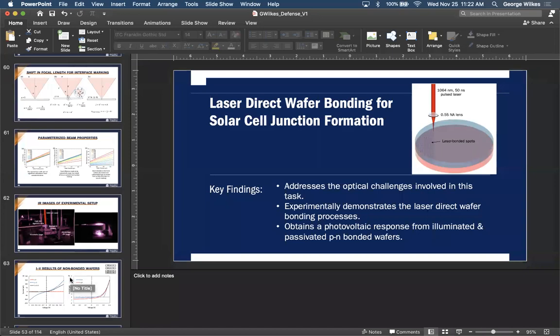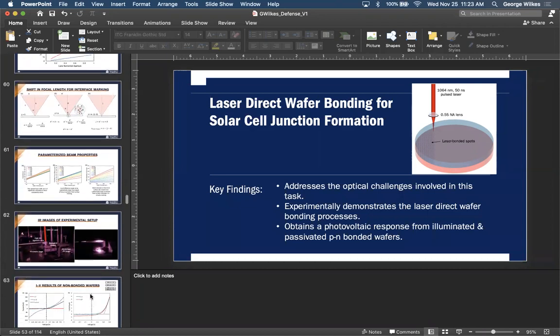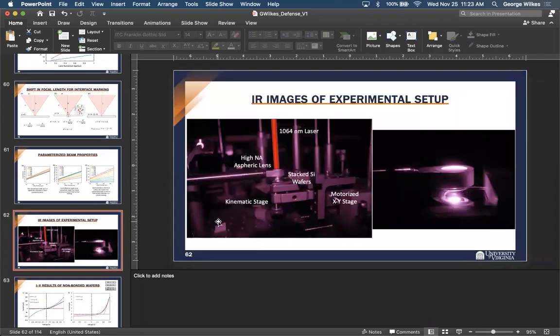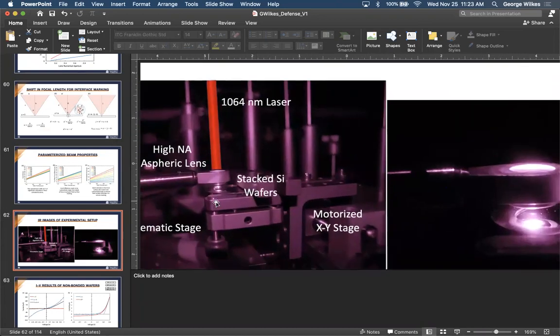I see. The other question is that usually when you do annealing bonding at high temperature using those wafers, they sometimes apply some pressure to keep the interface squeezed. Have you done that, or did you just place it and anneal it? Because I used the water, I did end up applying some pressure, not really pressure, but I used a small weight on top of the sample to push the two together. If I just used the water, one would be floating on top of the water.